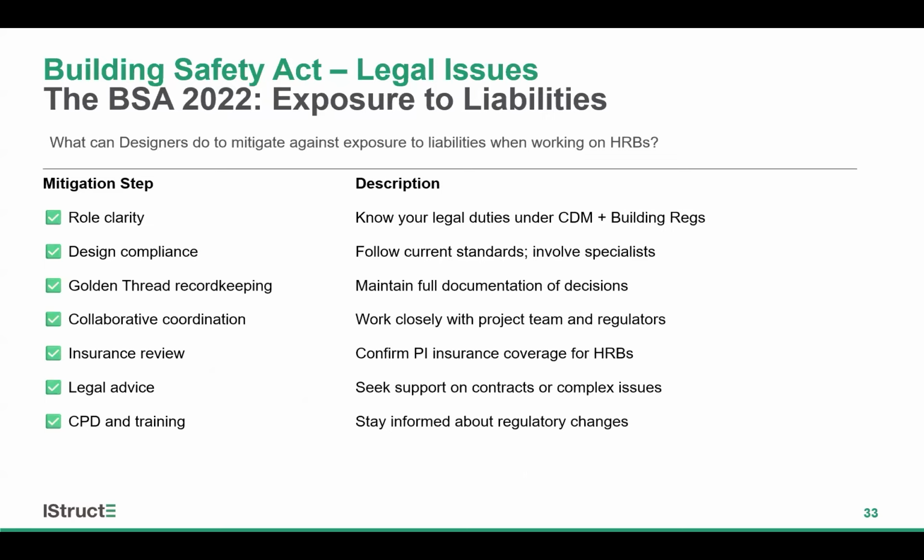So how then can construction engineers mitigate their exposure to this additional risk, which they are burdened with by virtue of the Building Safety Act? Again, to repeat myself, the requirement to obtain clarity on your role within the project and to know what your specific duties are is key. Make sure they are properly recorded in your scope of works and appointment documentation, and take care to bottom this out at an early stage. There's obviously a requirement for there to be design compliance. Obviously, you need to make sure your designs comply with the specification and all applicable standards, but do involve additional specialists to assist you if needed.